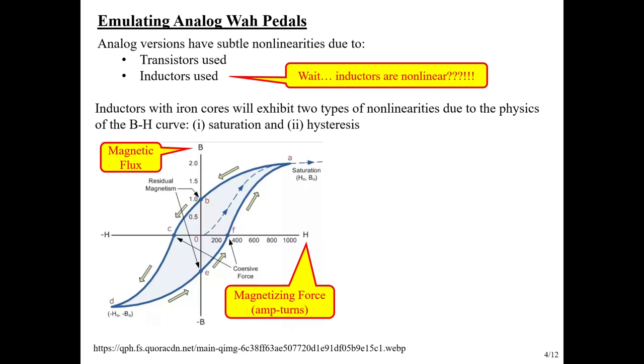And so if we doubled H, we would double the amount of B that we got. But here's the thing, because of the actual physics of this, the curve that the B follows as we adjust our current to get the magnetizing force follows a weird kind of S-shaped thing. Almost looks like the F hole on a guitar. So that's one way to think about it. But suppose we started here. Actually, if we first start off, we would start here. We've got zero current flowing through it, and we get zero magnetic flux.